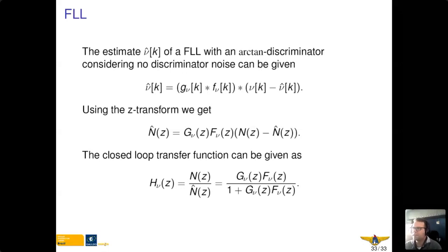The design of the loop filters and so on, you can maybe continue reading in the literature. This is not a so easy field. A lot of people already take coefficients of these loops from the literature. There have been people deriving optimized loop filter structures already, and you can just take the coefficients from tables and introduce them to your loops, dependent on values, for example, the loop bandwidth, the damping factor, and all these things.